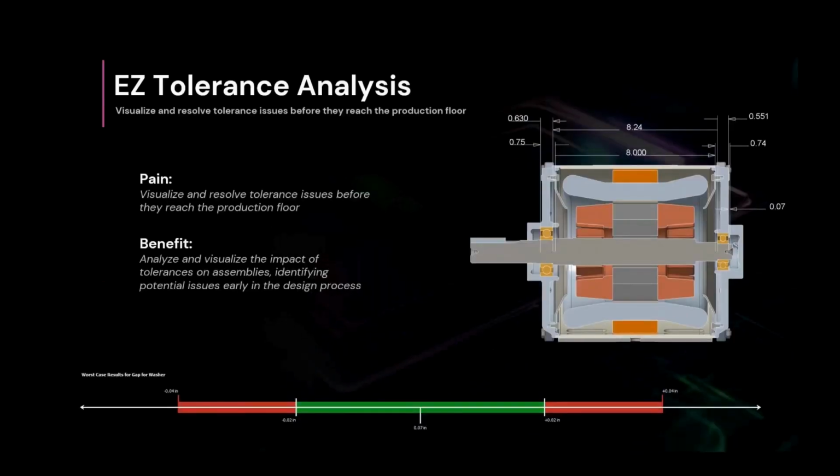So tolerance stack-ups then are a pretty critical process for ensuring that your assemblies function as intended. But traditional methods can often involve manual calculations, or external tools, again, which can be quite time consuming and prone to error. You're introducing an error whenever a human aspect comes into things. You're always going to introduce potential errors. So by embedding this tolerancing analysis functionality directly within Creo, it can help you make more informed decisions early in the design process and reduce the risk of costly revisions later on.